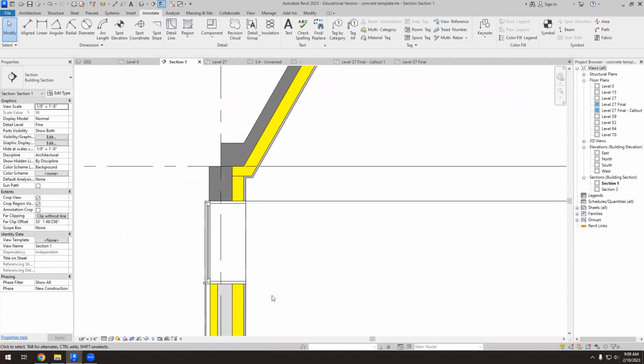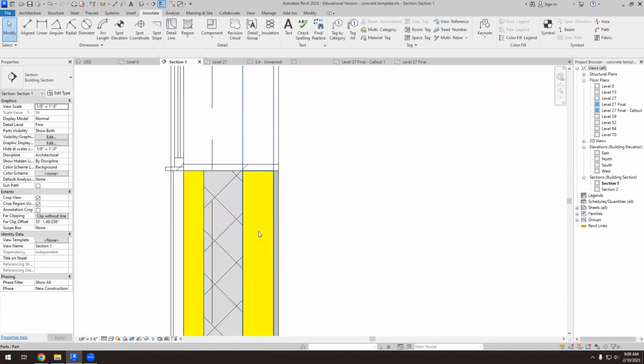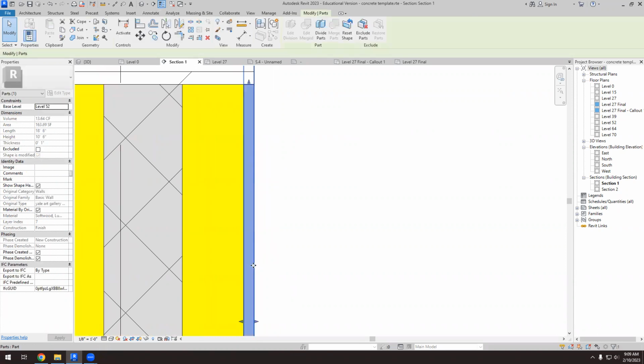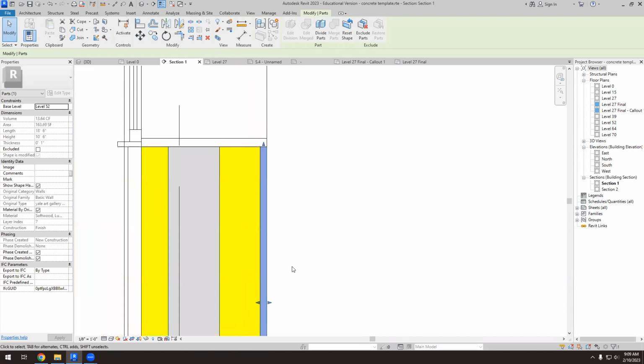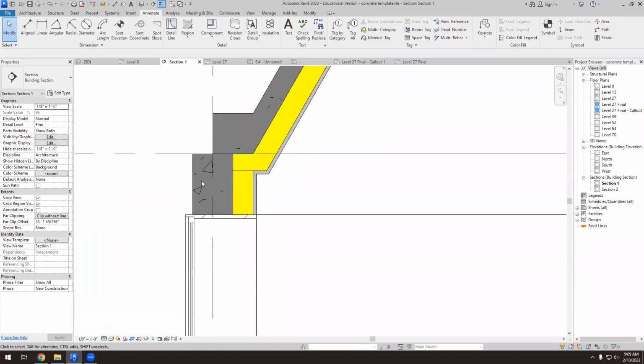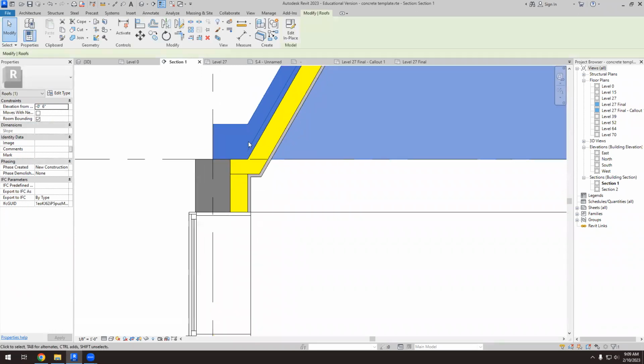So this is a better detail because here in the wall, I have the concrete masonry unit, thermal insulation outdoors, thermal insulation indoors, and this can be the plywood, or I don't remember, I think it was plywood or wood, the interior finish. Here in this pyramid, I have the concrete element, which is the beam. This is the concrete pyramid that didn't have any thermal insulation.